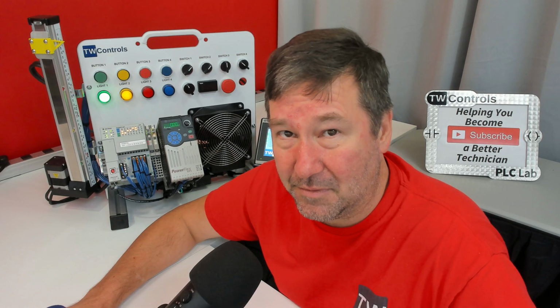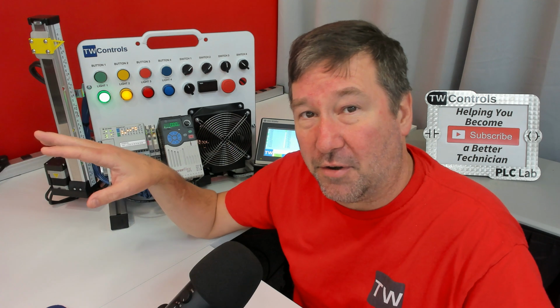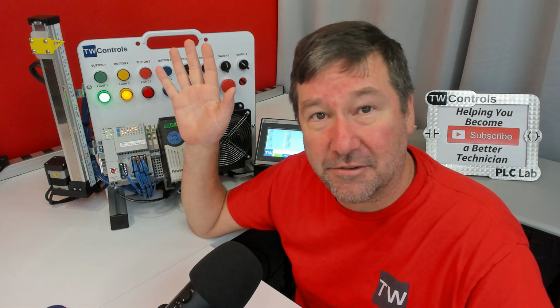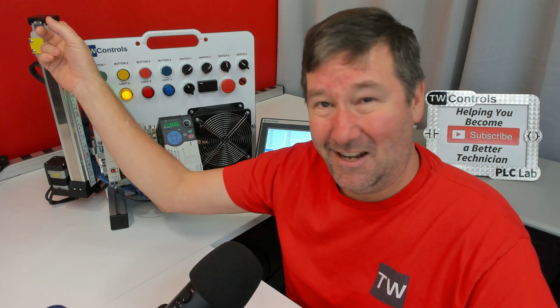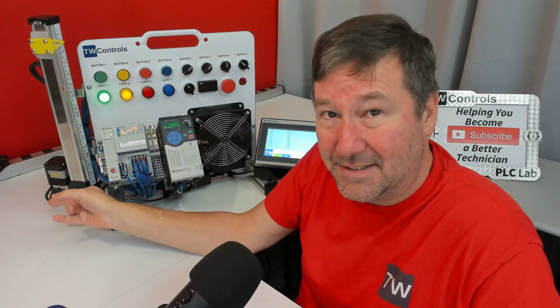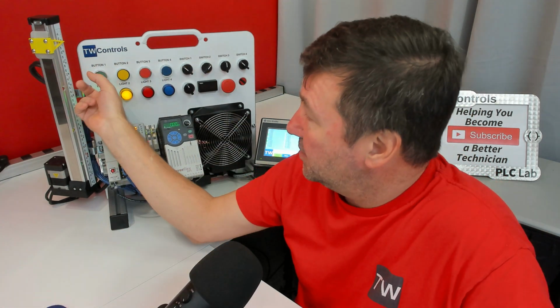The manual or jog mode does not work perfectly because with the virtual axis, there are no limits. You can jog to infinity and beyond. We have limits here. We can only get to 300 millimeters. We can only get to 0 millimeters. So I'm at 300 right now. I'm going to switch one. That's going to let us use the green button to jog up.